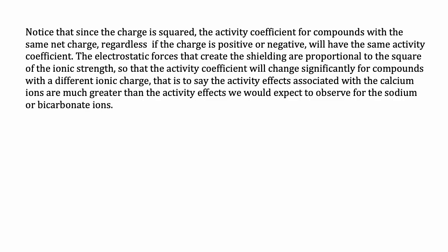However, in most of this course and most of the rest of the textbook, we'll be assuming that the total dissolved solids concentration is relatively low and that the activity effects are relatively low, such that for most freshwaters we can usually consider them as if they were an ideal solution and assume that the activity is essentially equal to the concentration in solution.